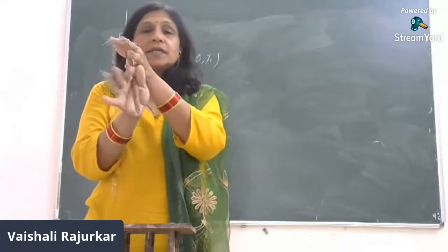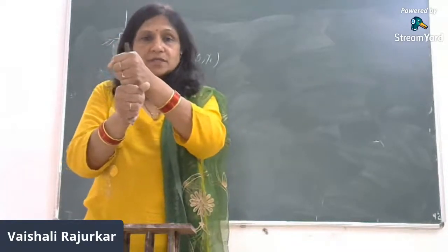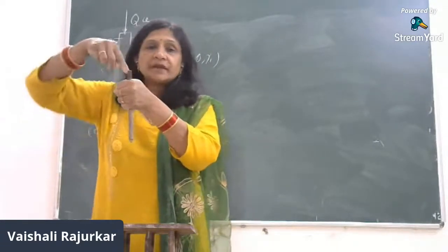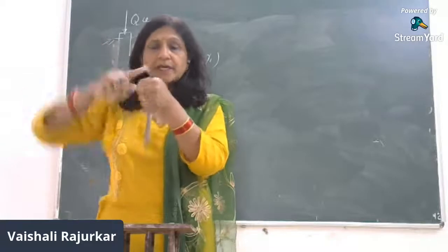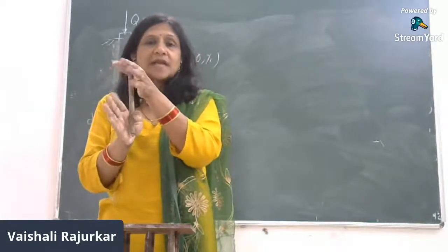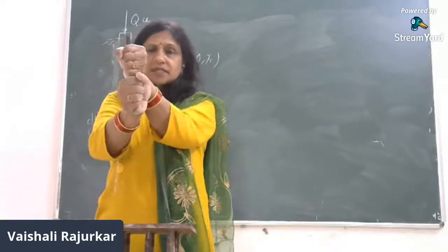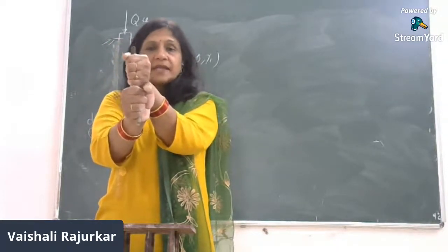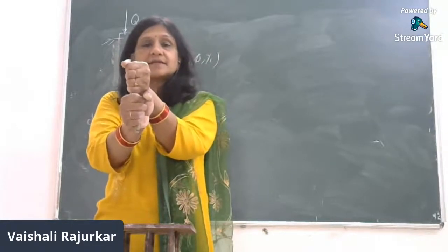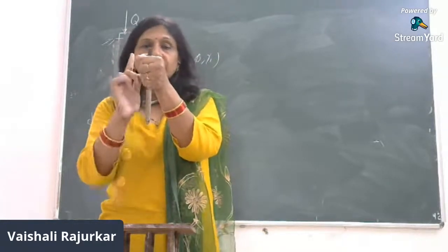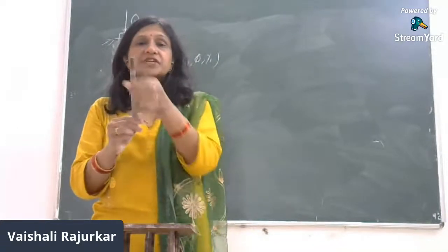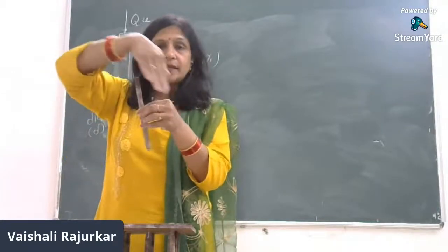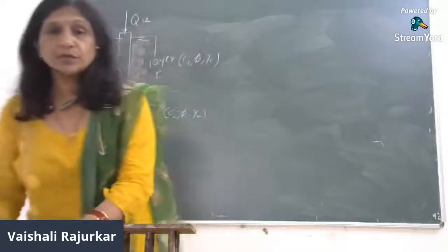Now you all know this pipe is being embedded into the soil. When we are trying to push this into the soil, there is frictional resistance due to the surrounding soil, very similar to the action like this. So this soil holds the pipe properly and therefore it gives resistance against the ultimate load or against the penetration, that is the frictional force which is developed around the periphery of the pipe and into the surrounding soil. So the load is taken by two parameters.